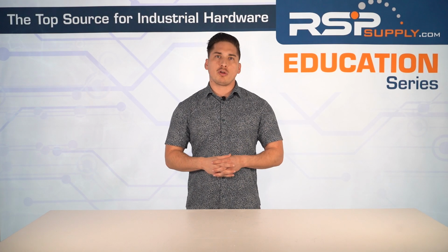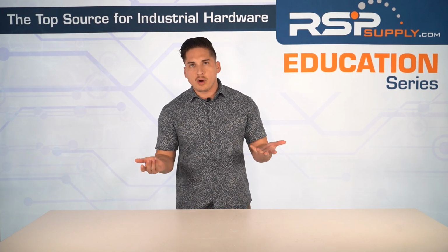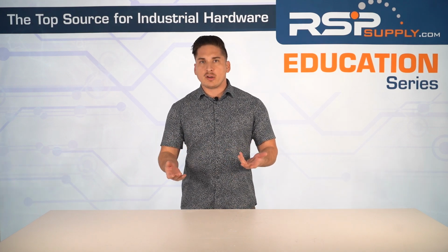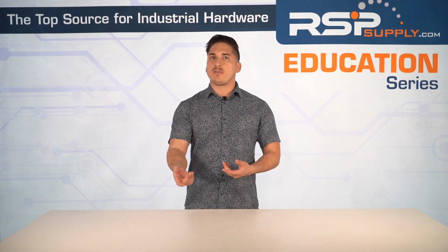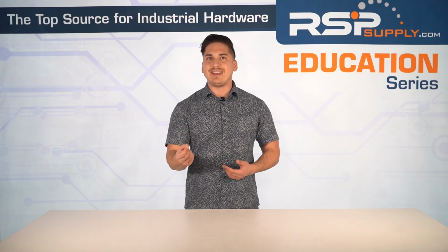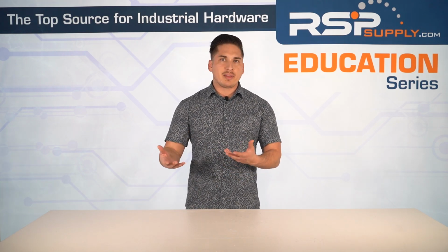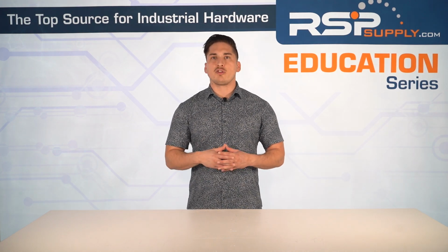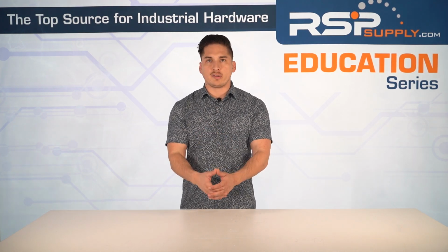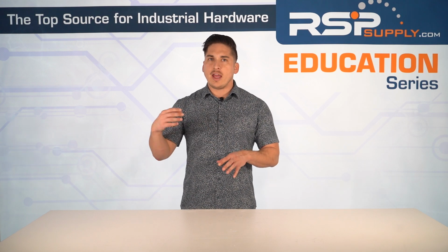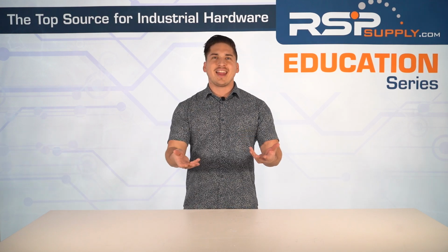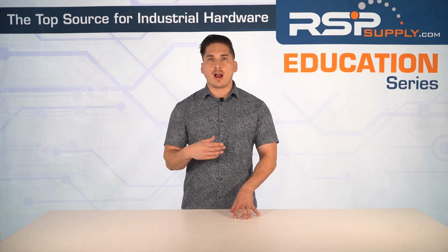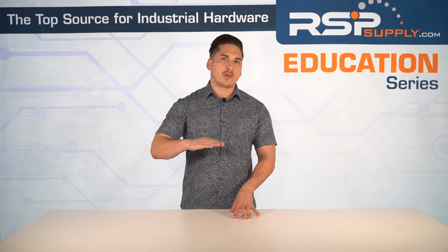Rectifying AC power is a crucial process in electronics. We use diodes in rectifier circuits, either half-wave or full-wave, or center-tapped or bridge diodes to convert AC power into pulsating DC. Filtering, by mainly using capacitors, is going to smooth out the pulsating DC, and voltage regulators stabilize the output voltage. This processed end result DC power is then used to operate a vast array of electronic devices and systems that rely on a constant unidirectional flow of current.